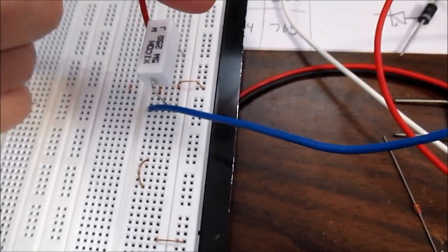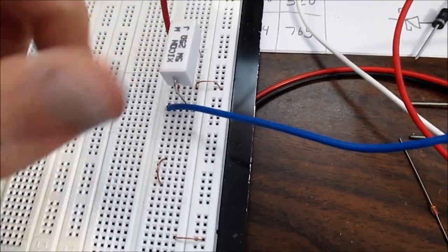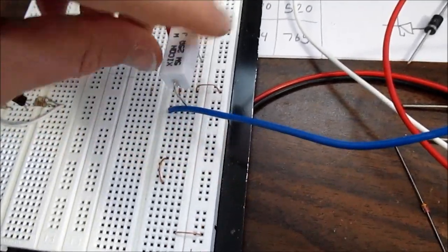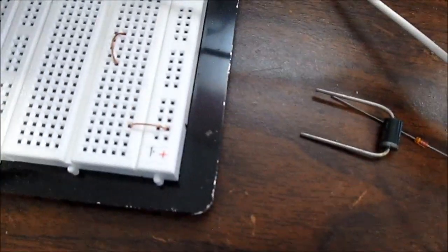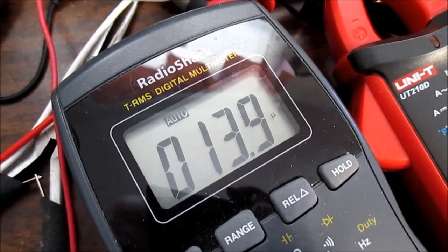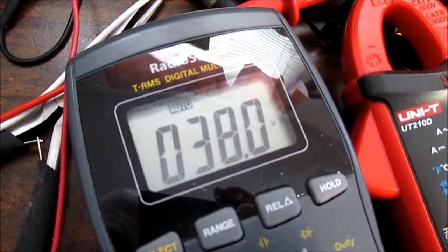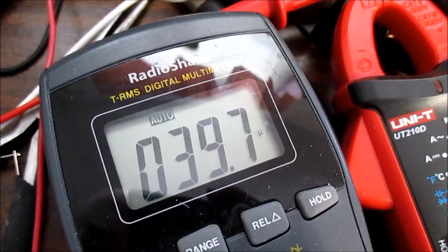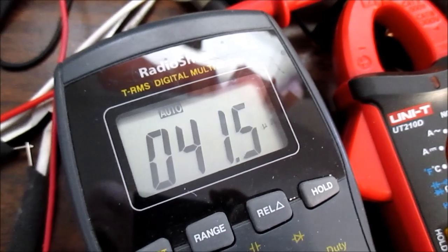Now let's see what happens. I have this resistor here. It has 5 volts across it, and it's 25 ohms, so we get exactly 1 watt dissipation, and you can still touch it. It's not real hot. So I'm going to put this diode on there and watch how the current increases. Okay, I let it go a minute and it's more than tripled its leakage current just from the heat. And it's still nothing serious, 40 microamps.